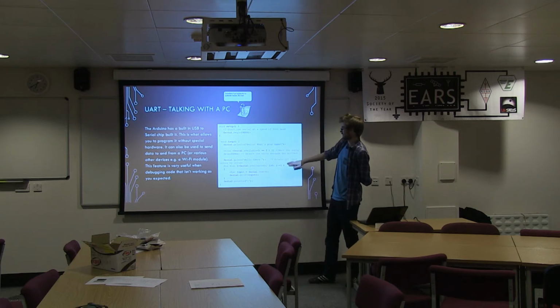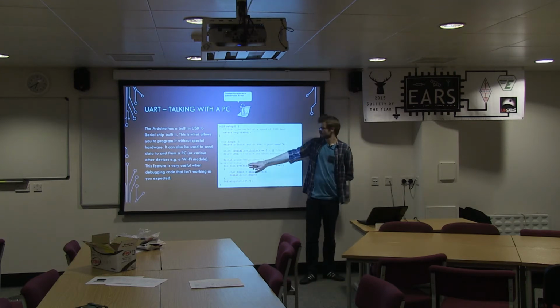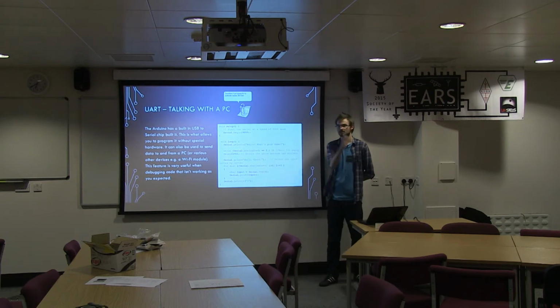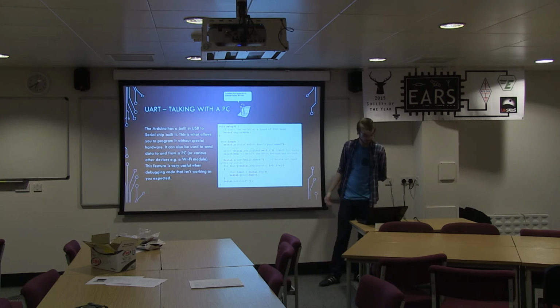Now this one is a Serial.print. The difference between print and println is simply that this one doesn't put a new line at the end. So if you keep calling print, it'll just carry on across the same line.